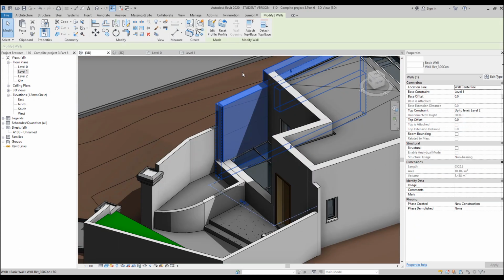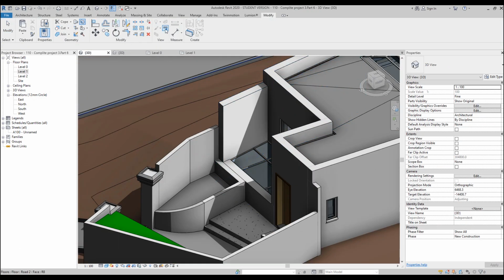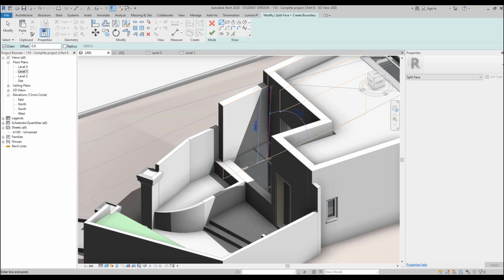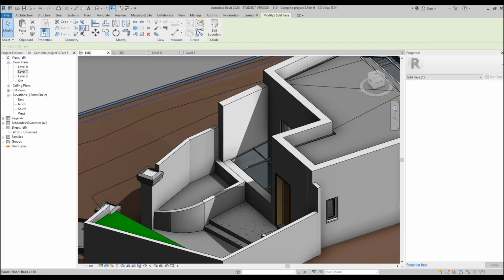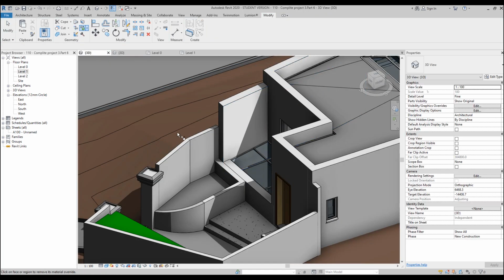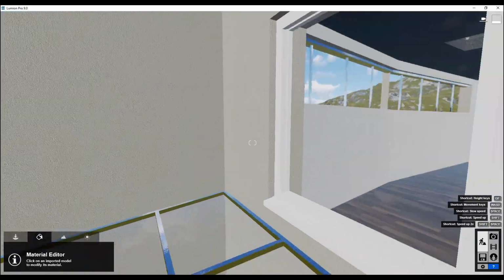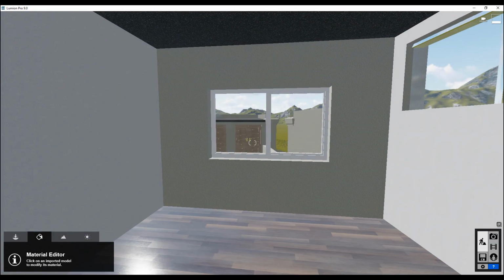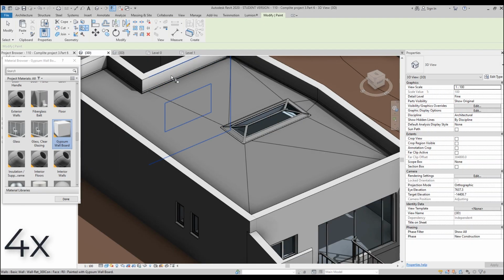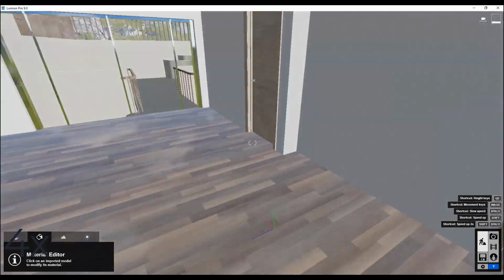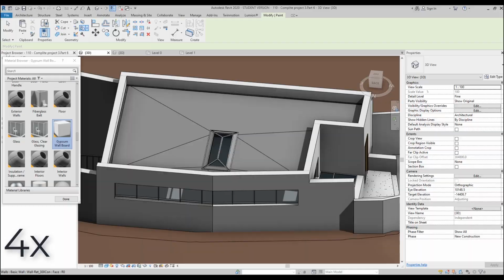I should divide the profile. Select your wall, select divide profile of your wall, say OK, and change the material of that. So here it will be just material. Let's do it. Here will be exterior plaster, there will be interior plaster. Let's apply interior plaster and check it out. As you can see, it's one wall, different plaster. And just go one by one. I'm doing it one by one, and as you can see, interior things, everything alright.